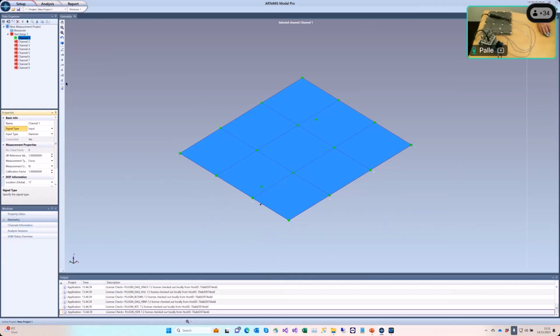And we also have to direct it in the right direction, because right now we have to be on the bottom of the plate and then impacting it in the plus Z direction, which is not very convenient. So I will change it here to minus Z, which means that I can make the impact going down into the table, you could say, in this case.